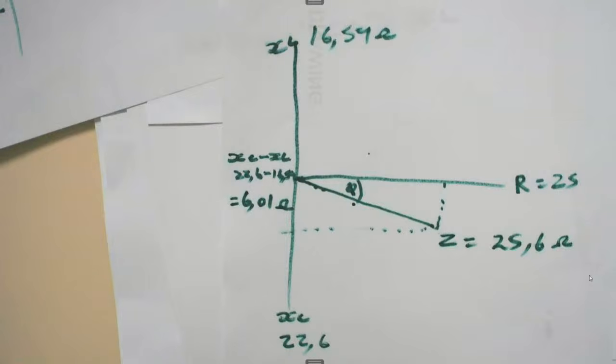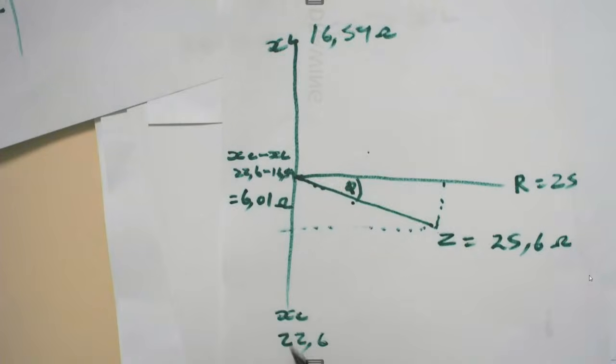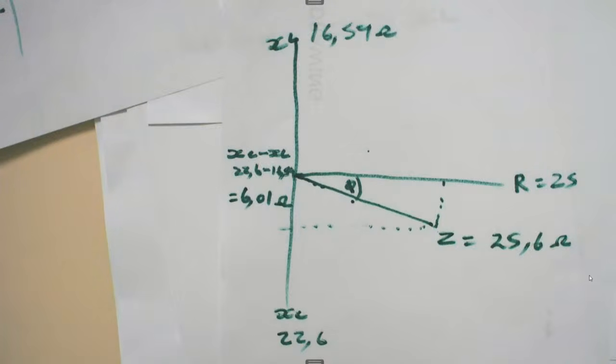So this is how you are supposed to do a phasor angle with your resistor and reactances. The same way if you have to do it with your voltages, because in a series circuit you'll have your voltages divided. You'll have an IL, IC, then you'll do it with the currents if it was a parallel one. Normally there's a question that would say calculate your reactance.